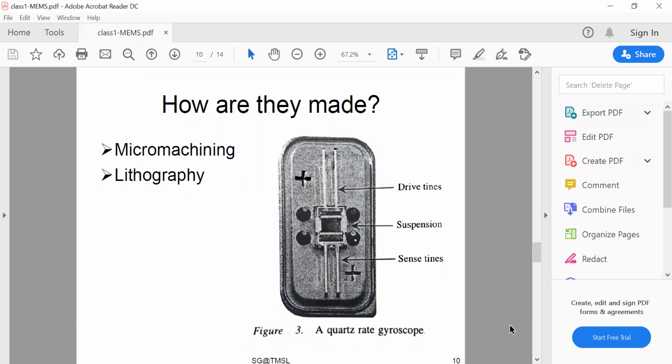Lithographic techniques generally require the use of a flat substrate. Silicon is often used even when there are no electronic components in the device, because the tools and instruments needed for microfabrication are designed to match the characteristics of silicon wafers. Lithography offers in-plane submicron precision on dimensional scales from micron to millimeter. Thin film deposition and etching techniques in combination with wafer bonding techniques allow patterning of the third dimension, making possible the creation of movable parts.